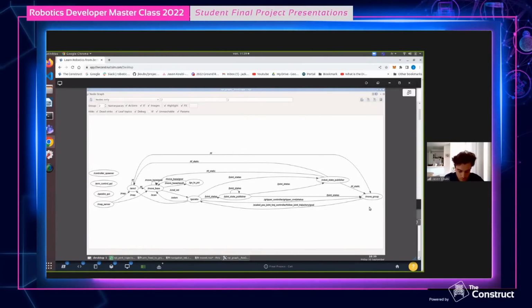Oh, okay. So you are not computing the odometry with encoders on the wheels? No, we wanted to do this, but the wheel encoders are not very useful here because I'm using the skid steer drive. It's like 4 motors, so it will allow the robot to slip, and this will not be useful for the wheel encoders if it's slipping.